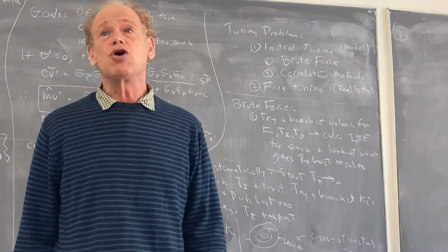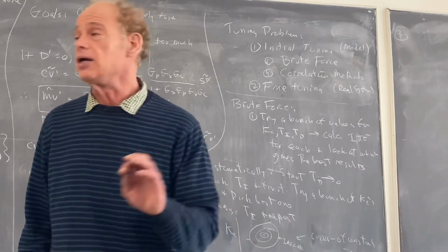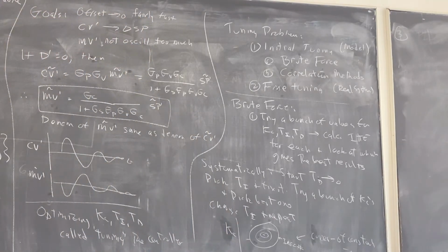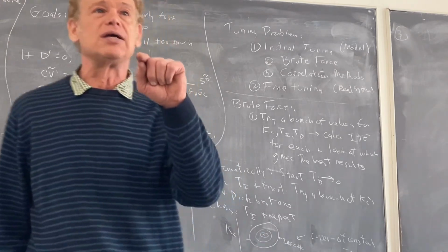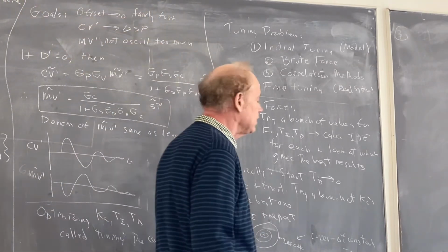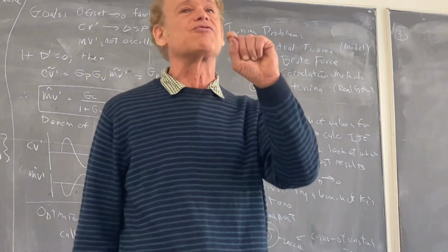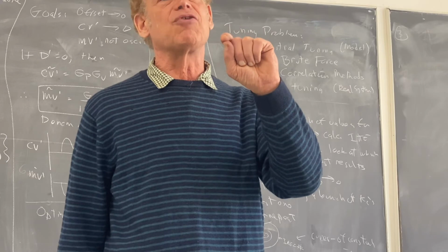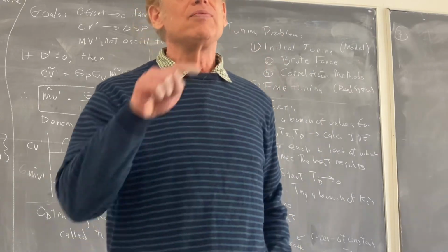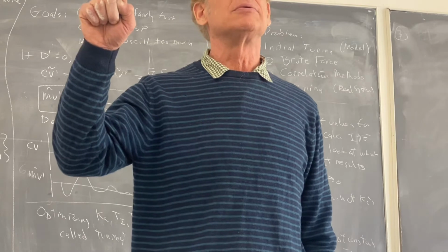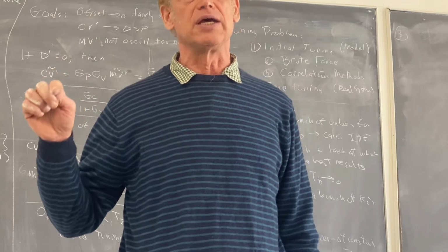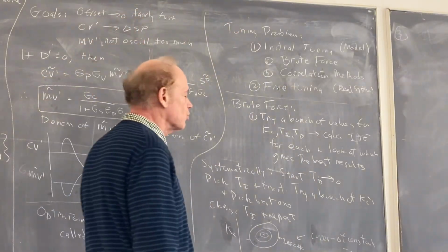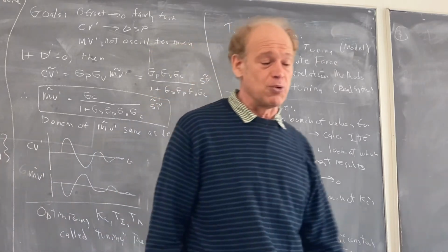Now, we'll talk about how to deal with TD afterwards. But as we said, TD is very sensitive. You never want TD to be particularly big. So once you have this value, for this KC and this TI, you can start increasing TD a little bit from 0 and see if IAE goes up or down. Chances are it'll start going down and then it'll go up. So chances are you can only increase it a little bit from 0 and then IAE will go to hell because things will get unstable. So that's how you would do things brute force if things work out in the best possible way.